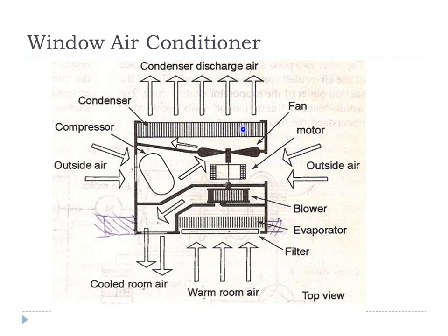Because the refrigerant is at high temperature, the outside air, blown by the motion of this fan, will flow over the condenser surface, and since the refrigerant is at a higher temperature than the outside air, because of the temperature difference the refrigerant inside the condenser will get cooled, and this air will be discharged at a comparatively higher temperature.